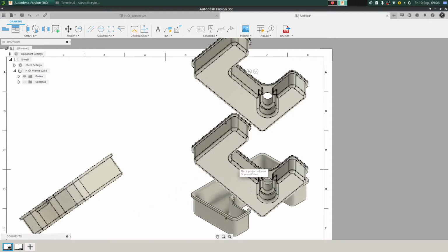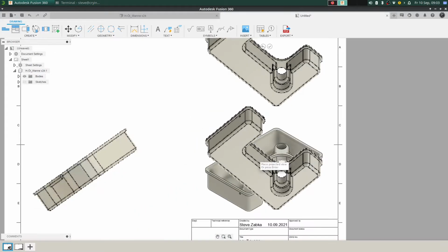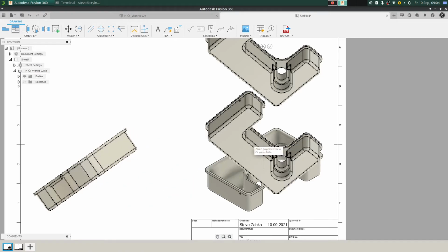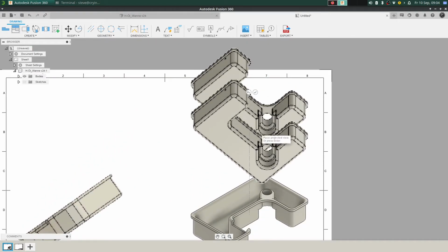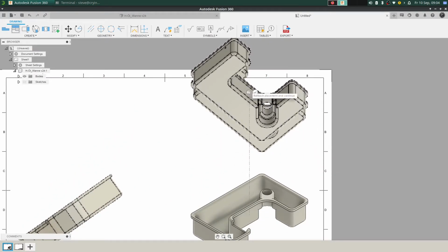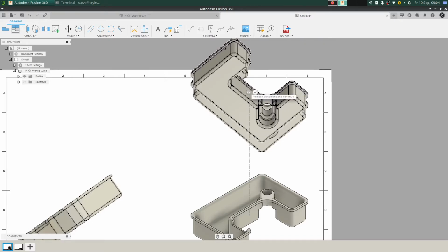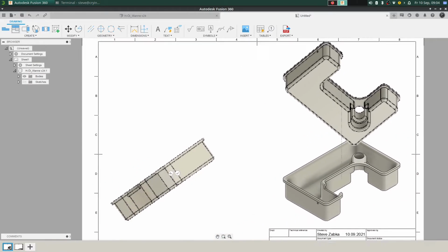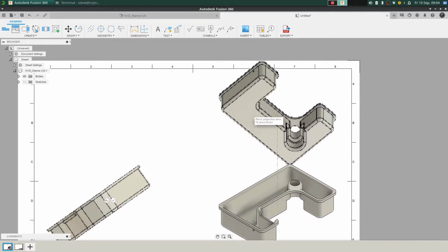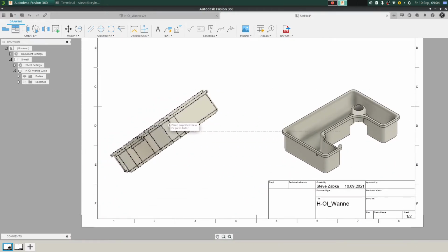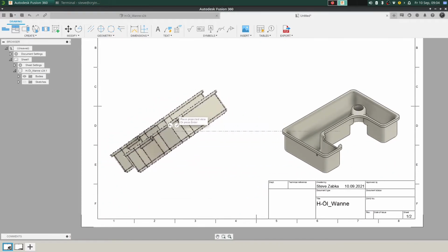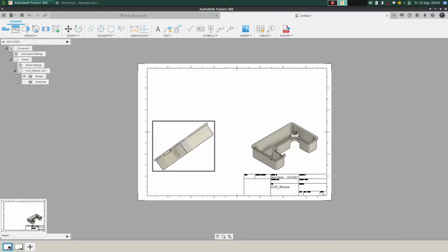So, when I will only create this view here and not this one on the top side, then I click here on rollback, placement and continue, and this view is now deleted, and then I click on create and continue, and we have a new one on our sheet 1.